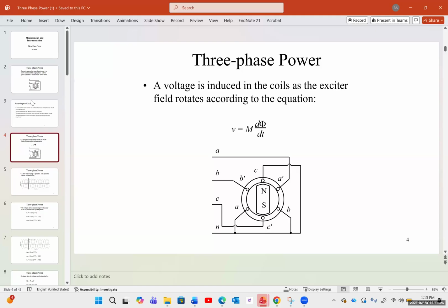The difference between that and a normal AC motor that you see in a HVAC system, the difference between their performance and efficiency is about 3 to 5%. So 3 to 5%, if you're using it in an EV, it would increase your range by 5%. Sometimes it's beneficial because when you increase the range by 5%, you can reduce your battery pack by 5%. So that offsets the price of the material that you put in.